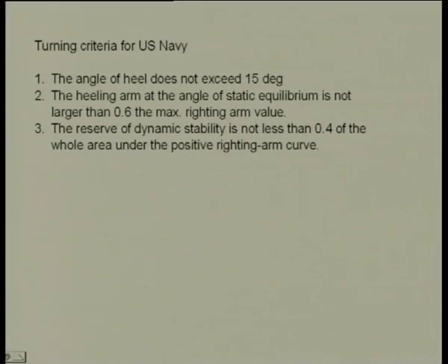Even in the turning criterion, okay, in the case of turning criterion there is not much of a difference. We will see here what is the turning criterion. Right here it is given. This is the turning criterion given by the US Navy. Now, it is very important that the angle of heel at any point during the turning does not exceed 15 degrees.